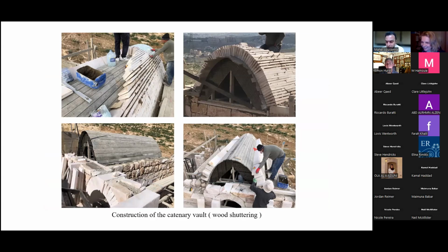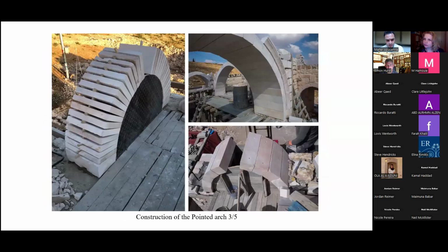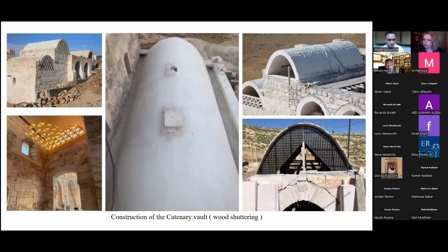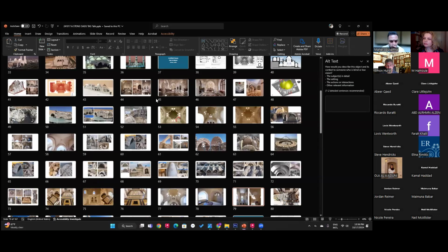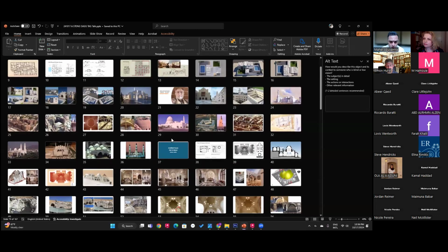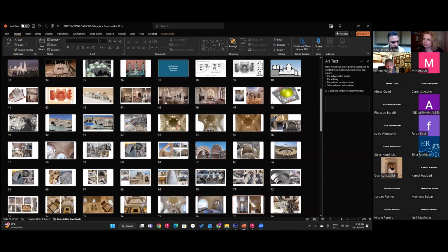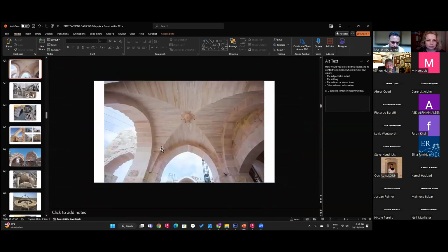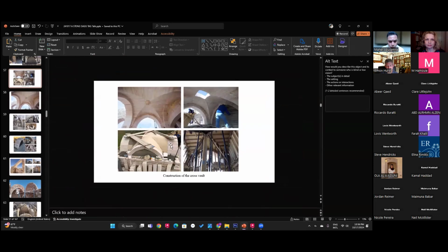Yeah, it's a very hard question. When I started building, I was good in computer 3D, I can draw stalactites and complicated geometry. But when I start working on site, say I want to do a cross vault, I search on the net, on YouTube. You can find pictures of a cross vault, but how you build it on site, on video, it's not easy to find. How to cut that edge, how to cut the stone to get these sharp edges. Really, it's hard. So what I did here, we have the formwork, because I built these four arches, continued that profile extruded and got the shape.